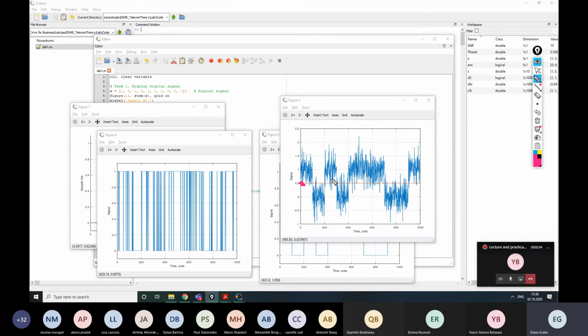So if we use it this way, we will have such, well, not so entirely clear picture, but we can see here that mostly this is 1. So yes, this is not a good detector. We will use a much better one when we calculate the energy of this signal, the entire energy average value, and compare this average value.